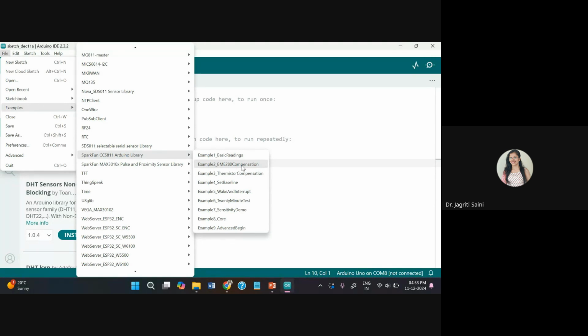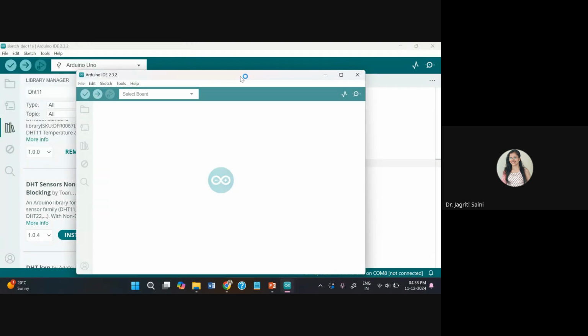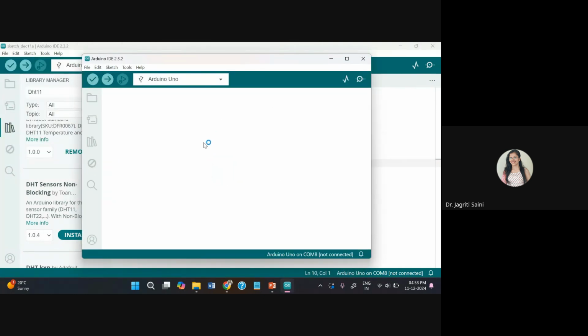It means we need to integrate our code in such a manner that it should first take a temperature humidity compensation and then measure readings from the surrounding environment by considering those thermal comfort parameters. So these are some adjustments you have to make for the accuracy of your measurement sometimes. And here, for instance, if you want to see how we measure basic readings from this CCS 811 sensor, we can visualize it with its example.